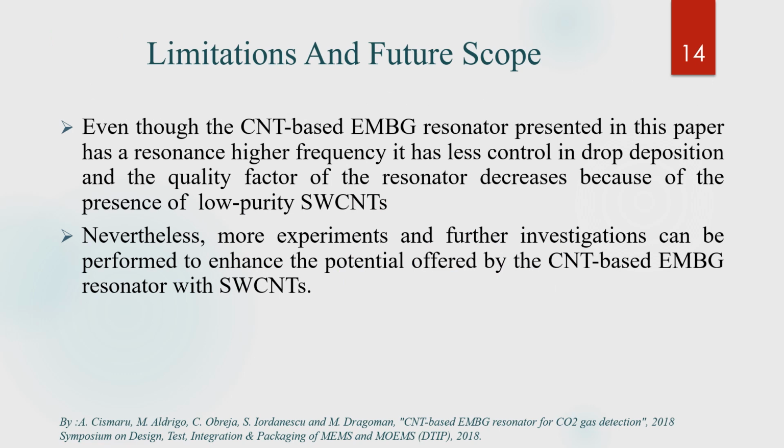Moving on to the limitations and future scope. Due to the presence of low purity SWCNTs, there is a significant difference as far as the resonance frequency of the device is concerned, but it made the device less controllable in drop deposition, and the quality of the resonator has decreased. But nevertheless, there is a lot of scope for more experiments, and further investigations can be performed to enhance the potential offered by the EMBG resonator along with single-wall CNTs.